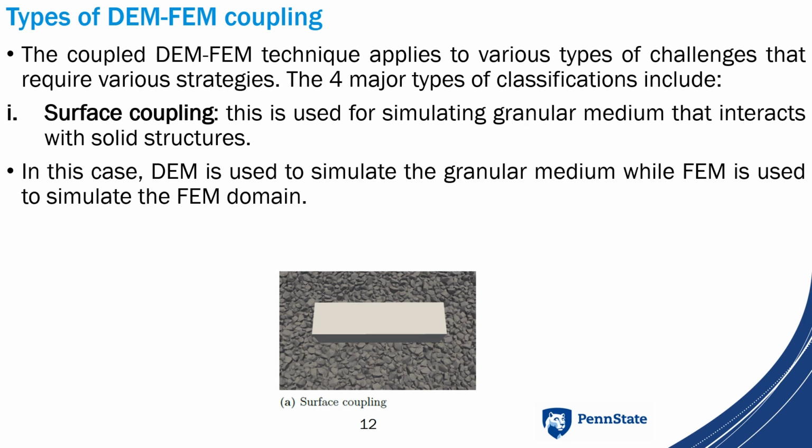At the interface between the FEM and DEM domains, contact detection algorithms identify interactions, while forces and displacements are transferred between the continuum elements and discrete particles to simulate realistic interactions. Through interpolation and averaging techniques, quantities such as stresses and displacements are exchanged between the two domains to ensure compatibility and continuity.